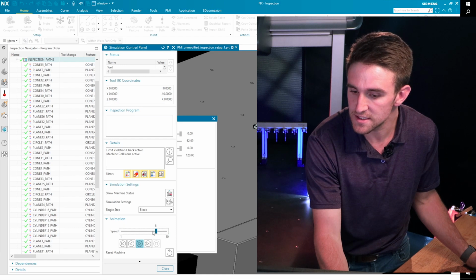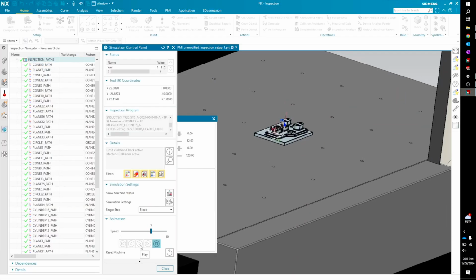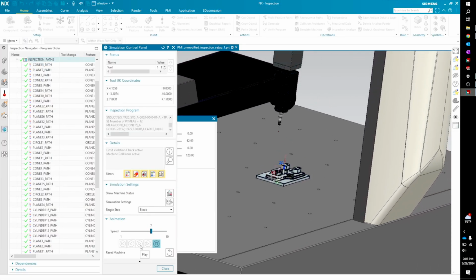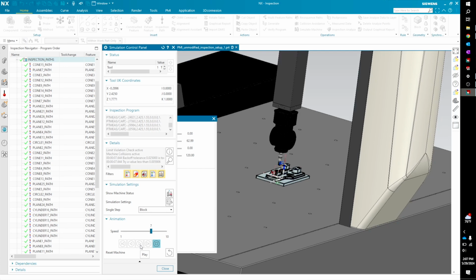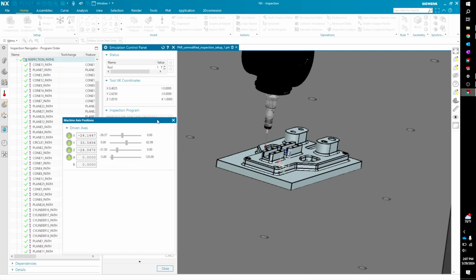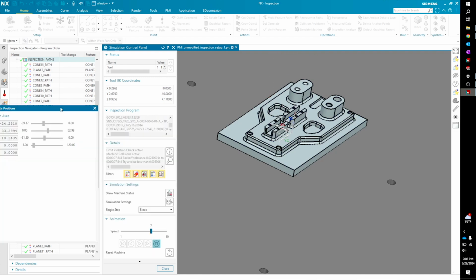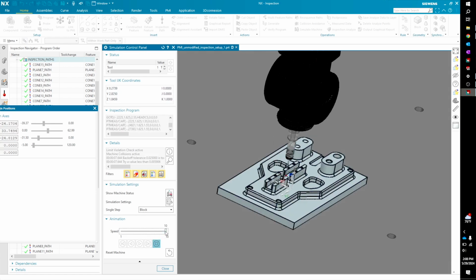I have the speed set to 7 out of 10 just for our demonstrations. And in a moment, we will see the Z slide approaching the part and we'll begin its inspection. So I can go ahead and zoom in on that some just to show what the probe is doing. It looks like it's inspecting the smaller hole features on top there now. It's changing the probe angle and going to do that 2 inches above the part as we specified earlier before. For our simulations, I can go ahead and just pick up this speed a little bit.